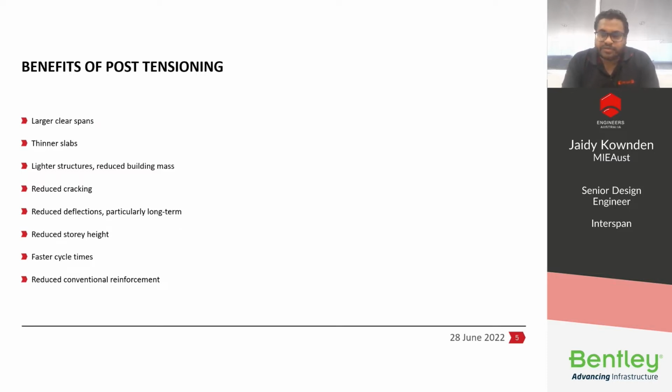Using post-tensioning also allows for faster cycle time. The earlier stripping of the formwork and reduced backpropping requirements enable a faster construction cycle and quick reuse of formwork. Once final stress is applied, formwork can be stripped and the slab can be poured in 3 or 4 days.